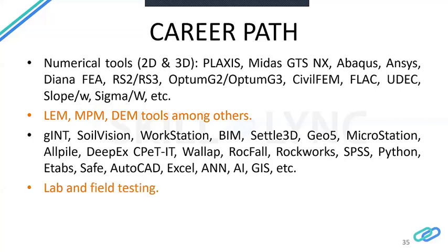For lab and field testing, you also have to be familiar with each lab and field testing procedure and what you can get from them, and if you need certain parameters for your constitutive model, what lab testing you have to consider, or what field testing you have to conduct to calibrate your finite element modeling, for example. And nowadays programming skills are crucial to some extent for foundation engineers to simplify the effort in designing the foundation using finite element or numerical analysis.